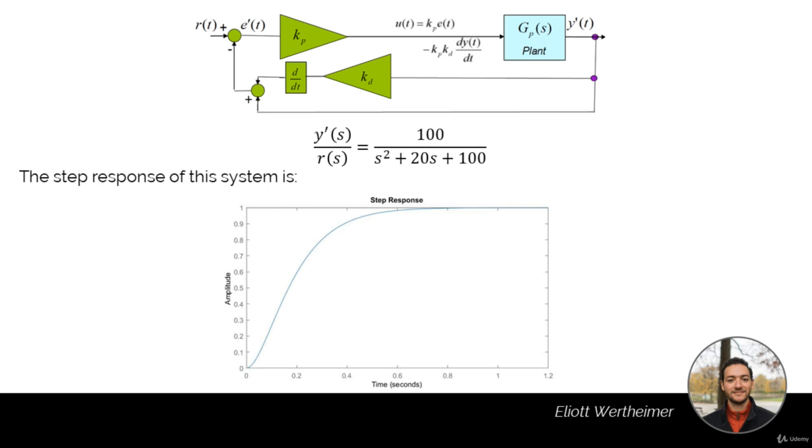And as you can see in the step response, we got a really nice response without any overshoot. Overshoots can be okay in some cases, but they can also be very, very important in other design projects. That means you really want to get rid of them. In this case, using proportional plus derivative feedback is obviously very interesting.